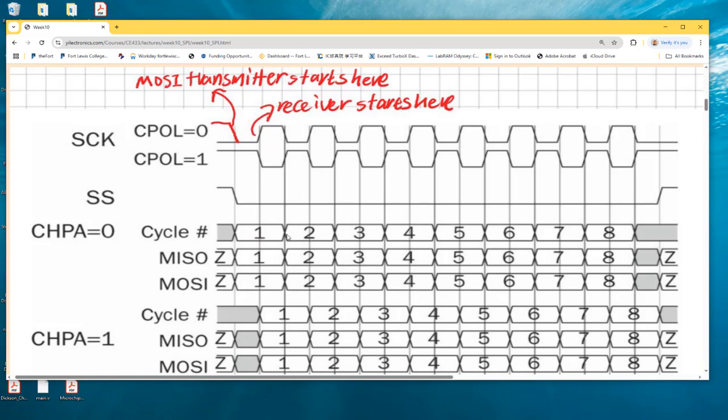You can see here's the leader, here's the follower, right? During the falling edge of the clock, the leader will drop the data to the data line, because clock and data are in different lines, different wires. So at the falling edge, the data will be available on the line. And then at the rising edge of the clock, the receiver or follower will take data in.